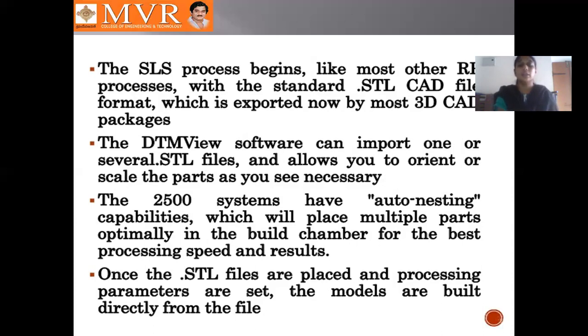The DTM View software can import one or several STL files and allows you to orient or scale the parts as you see necessary. The 2500 systems have auto-nesting capabilities, which will place multiple parts optimally in the build chamber for the best processing speed and results.